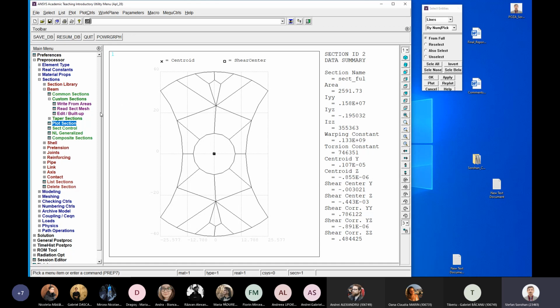Okay, but this is the correct answer for the problem for the complete structure, not for just a quarter. If you take a look at this one, the cross product area here, or moment of inertia as it is sometimes called for a cross section area, this one must be 0 due to the symmetry.